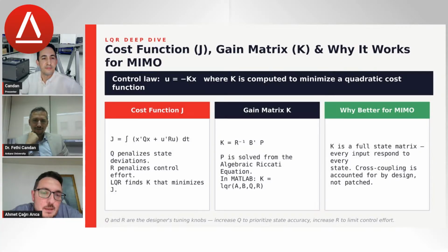And this system is an under-actuated system, and it has 3-axis motion, and there are 2 motors, and therefore we regulate the 3 axes, but we track the system in 2 axes. Therefore, if you want any LQR or optimal control, you must be careful to design the controller.